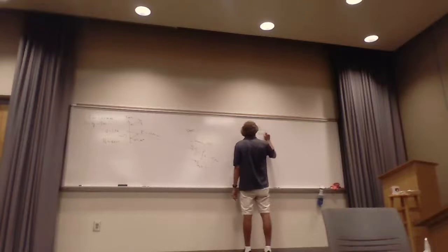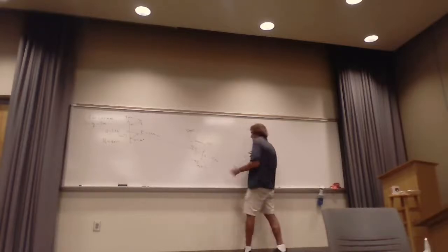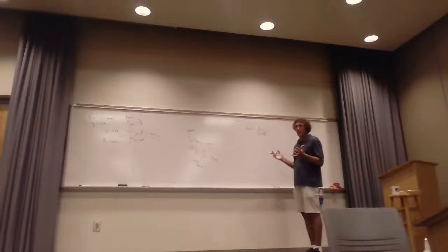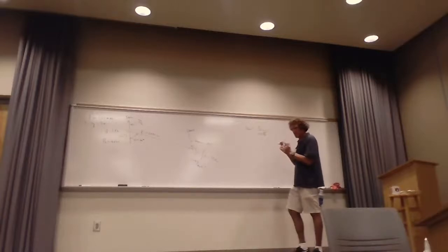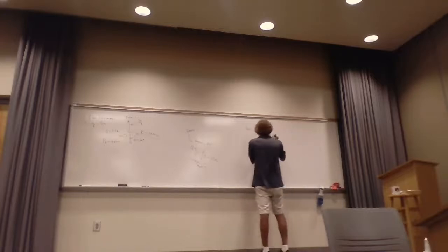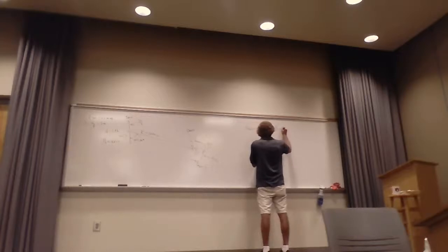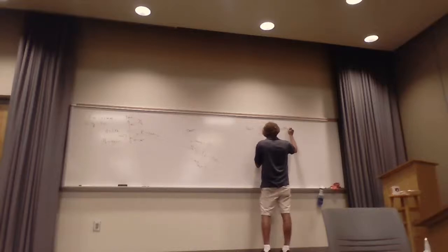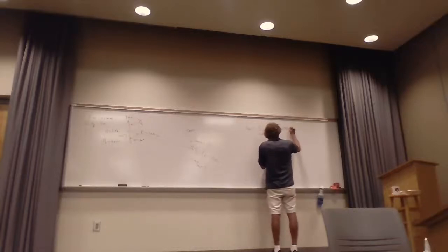Now, this is the way I always do these. I start with the isotropic power density at that point. Then I sharpen it up by the gain of the typical antenna. For this antenna, the gain is going to be 1.64. This was put down in there. And then it's going to be times the quantity cosine of pi over 2 cosine of theta over the sine of theta, and this whole thing squared.